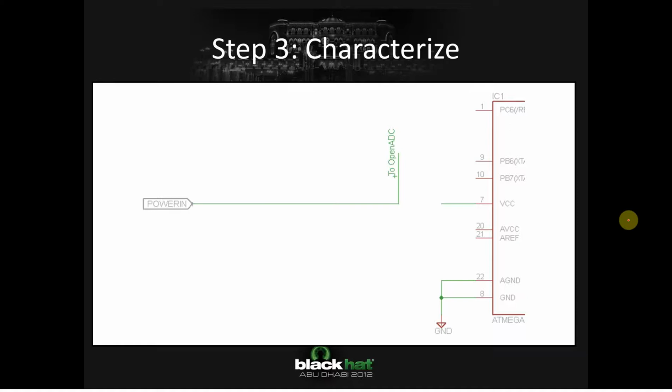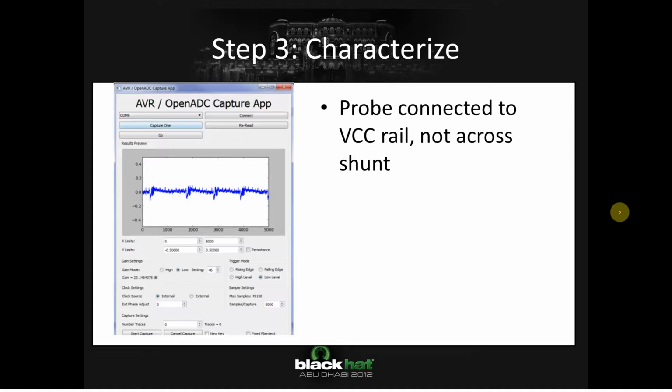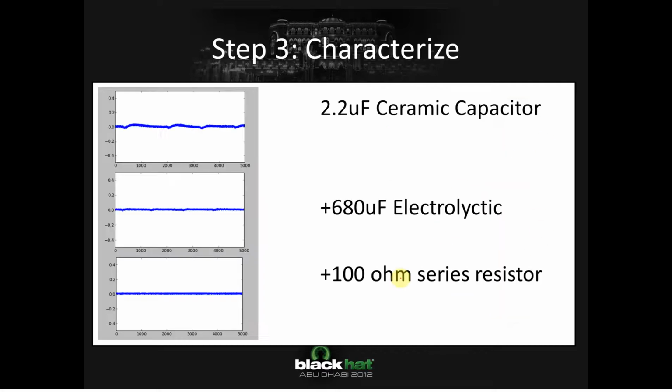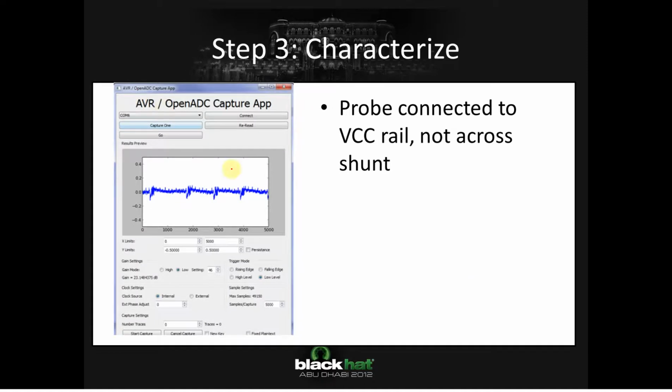So here what I've done is I've connected just the OpenADC, so the capture firmware, only to the power supply. The AVR microcontroller, for all intents and purposes, isn't even hooked up. And what I've seen is that there's a lot of noise here. This is very bad. This would ruin your results effectively.